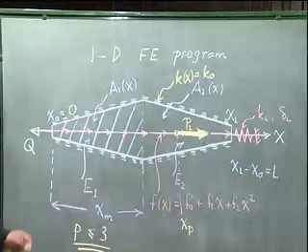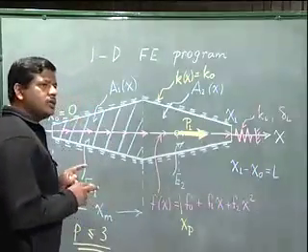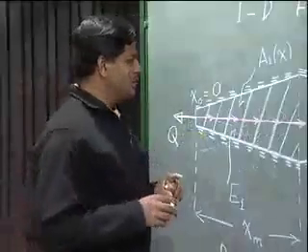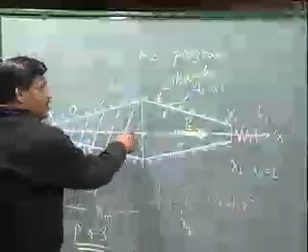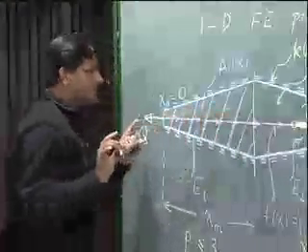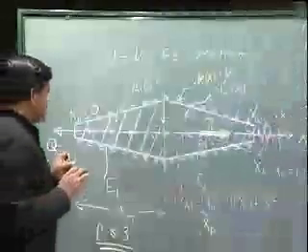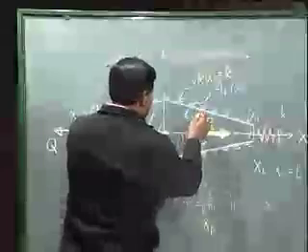If you look at this problem, as far as making the mesh is concerned, we have to honor certain boundaries. Which boundaries do we have to honor? This boundary where there is a transition of the cross-sectional area or the material, we want both transitions to be the same. We do not want them separate. Another boundary is here.